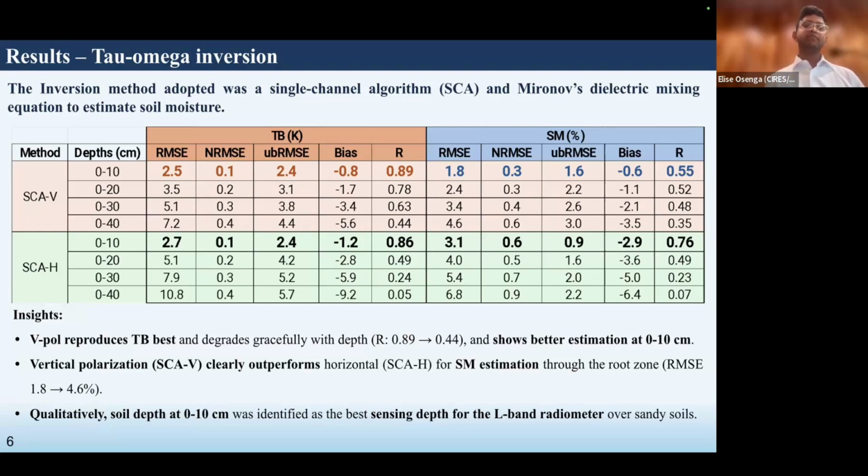So for quantitative analysis, we have done another study where we have mounted this L band radiometer over a tower, and we have collected the data for a period of 3 months and identified the dynamics. So we identified a few things. SMAP assumes equilibrium time of 6 a.m., which is not similar for the field scale study. Another, SMAP assumes the emissions are coming only from the top surface, which is 0 to 5 centimeter. But in our case, from the tower experiment, the emissions were coming from 7 to 15 centimeter depth.